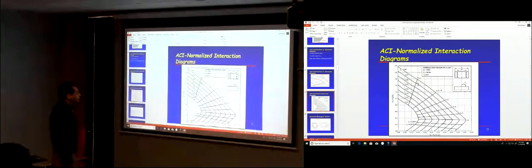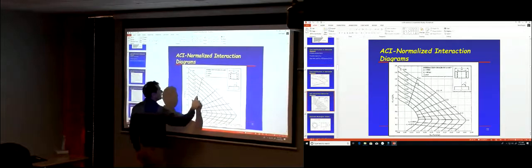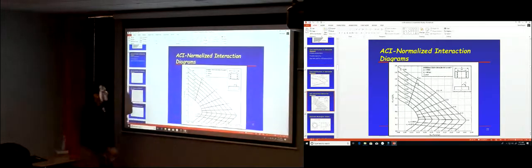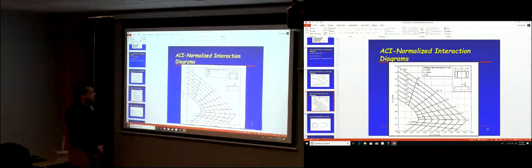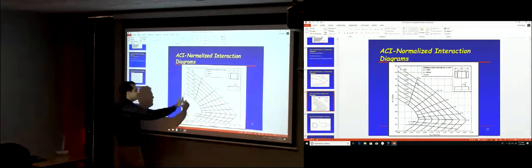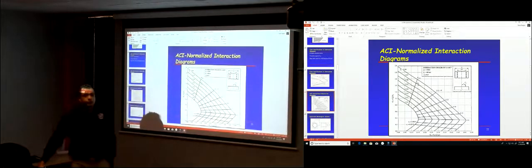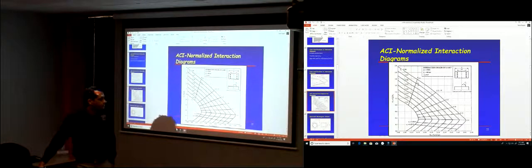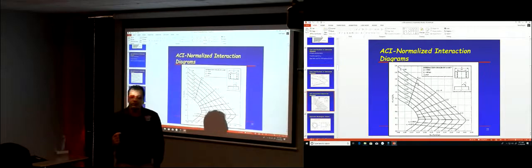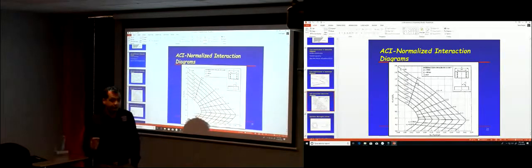What other lines do we have on this curve? This line is very important. K max. What's K max here? As you see on the vertical axis, we were plotting Pn, right? According to the ACI code in chapter 9, we said there is a factor of safety alpha that we have to take to account for accidental eccentricity, right?